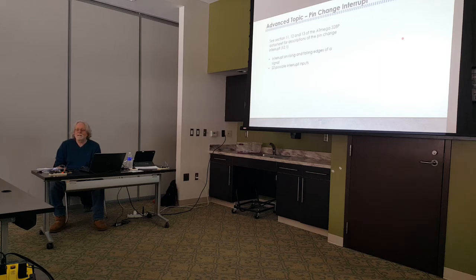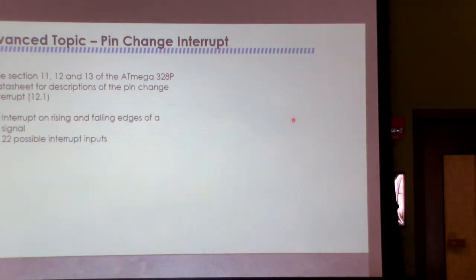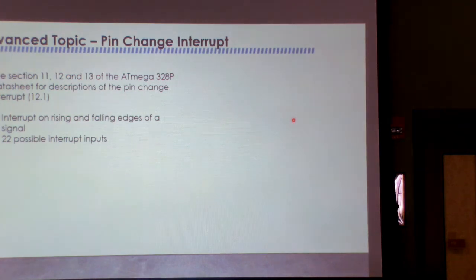This is the case where you will see every bounce if you don't debounce your keys. Every little jiggle of the line when you push that button or release that button will create an interrupt. So if you push the button and you get a close, open, close, you're going to get 3 interrupts on the close of the key, and then when you release the key, you get open, close, open, you're going to get 3 more on the output. So you need to either handle it in the software, or you put a capacitor on it, and you keep increasing the size of the capacitor until it fixes it. Not always a good idea.